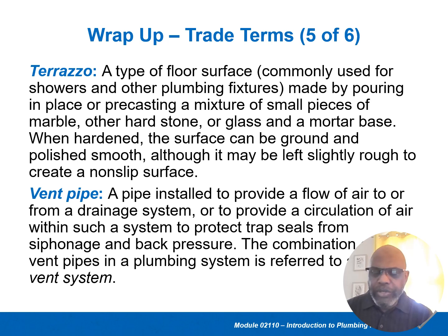Matter of fact, you can always tell if it's an extremely windy day outdoors. If you look at your toilet and you see the water going up and down, that's because that vent pipe outdoors is trying to balance the pressure from indoors to outdoors, and it will cause it to move back and forth sometimes. On a normal day, you would never see the water moving.